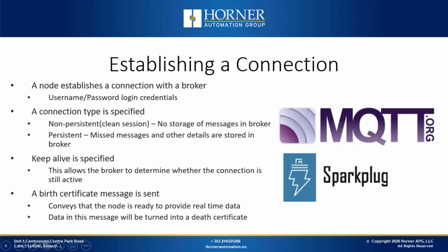As we're establishing a connection over MQTT, there are a couple of things that happen. The first step is the node has to log into the broker, so we'll have to know the username and password, as this ensures only certain devices can gain access. During the process, the broker will effectively be running on a computer over Ethernet. The next thing that's defined is whether it will be a clean session or not. A clean session is a non-persistent connection, meaning if messages are missed, they're not stored in the broker, but are lost forever.